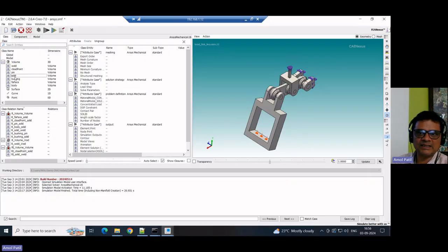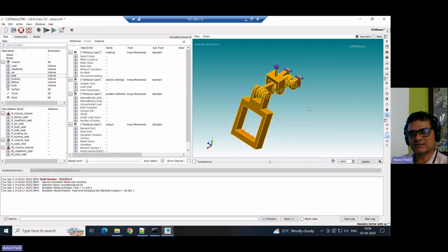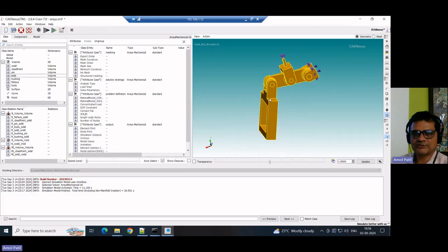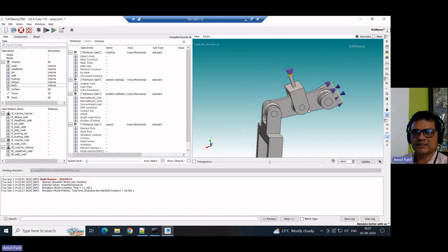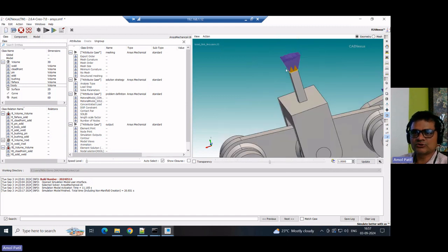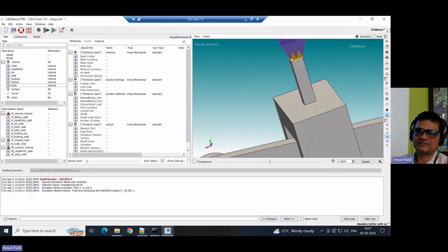So here, if I click on the solid, now it will start highlighting different solids, which are specific to this problem. So all the solid element set or solid 187 attribute will go on these solids. Or let us say in this problem, there is the body. So here it will start specifying bodies which are being used to specify these constraints.